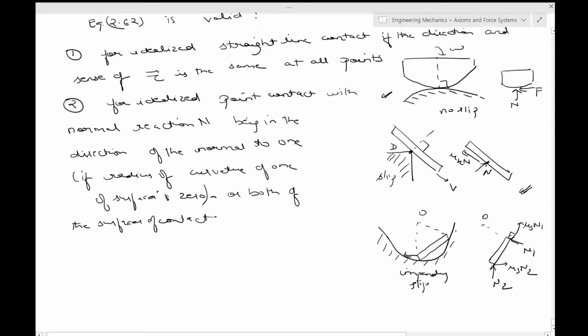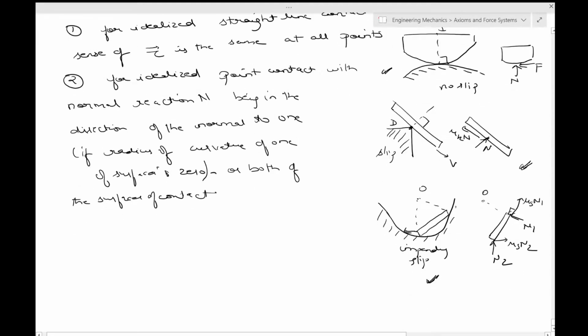Okay, but over here, which is a two-sided constraint, okay, this rod has constraint on two sides, you may not exactly know how friction acts. So in that way, just assume 1 and see if you get your value of n as non-negative. If it is, then it's okay. If it does not, then you have to try again with n equal to 0 and sort of go ahead. Okay.